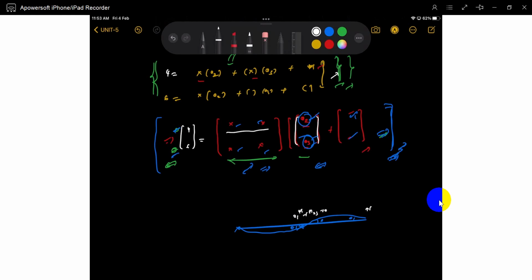You will understand later. By the deep meaning, if it is restricted here, the force will generate a moment. If you allow the rotation, there is none. The same thing here also. If you apply a force, there is no support, there is no reaction.